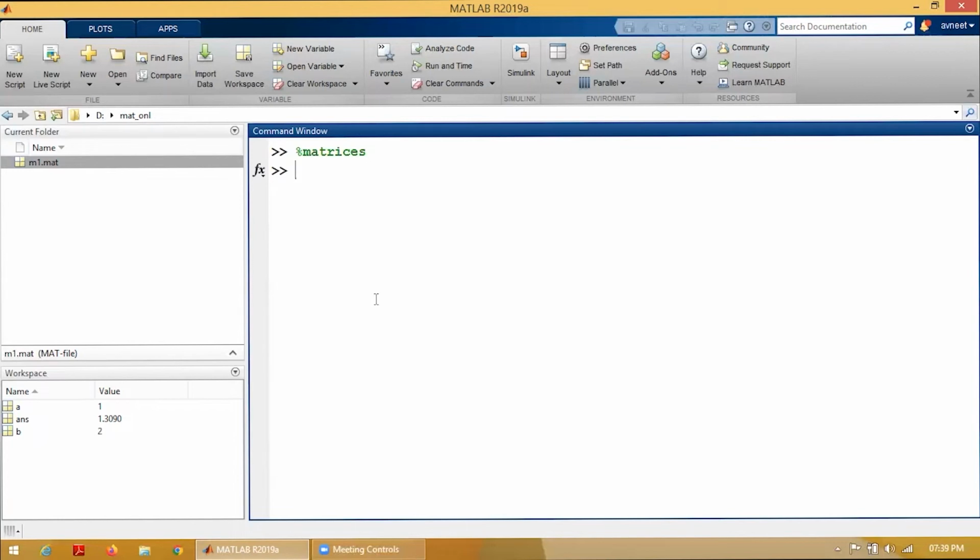All right, so how can I enter my matrix? A equals square bracket. Please use square brackets, and let's say you have some data. You can use space or you can use comma. Both are the same, and I'm using semicolon in between. I'll just show you. I'm using space here, see, two times, and semicolon here. Again comma and space here. Let us see what my result is.